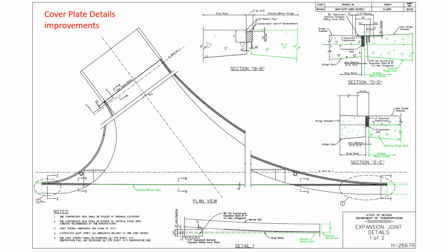There were some difficulties, where you can see the sections in the circles on both left and right, where you intersect the existing bridge. The material that we used to join the bridge to the existing one is just a compression seal material. So this bridge moved independently from the existing one.